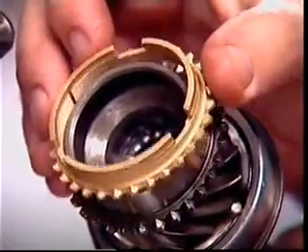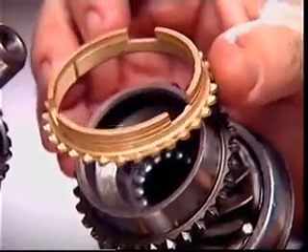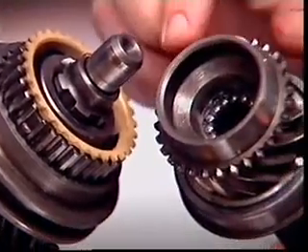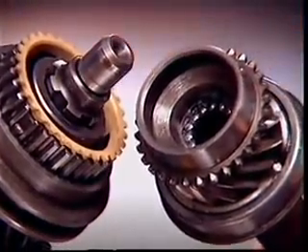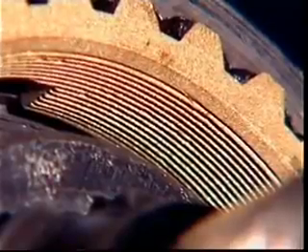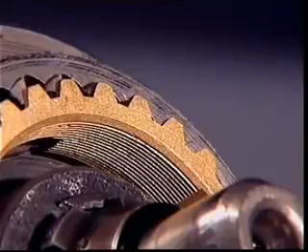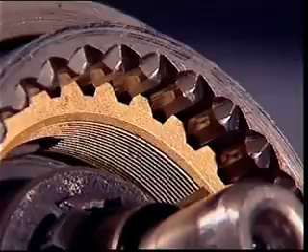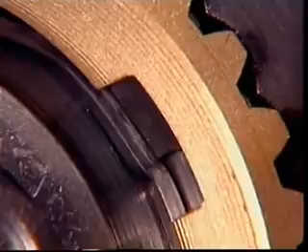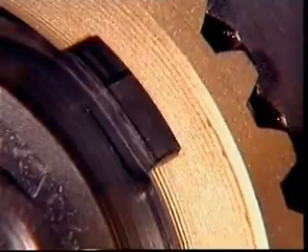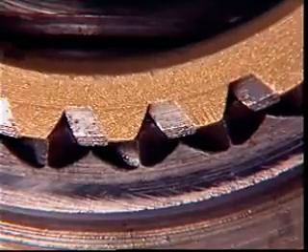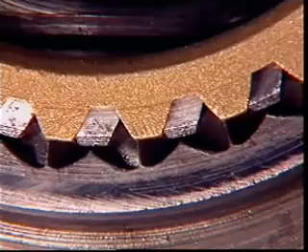A bronze balk ring with recesses to accommodate the ends of the inserts is located in each end of the hub, and a conical inner surface faces a matching steel cone on the gear. Fine grooves are machined on the conical surface, and the teeth on the outer edge are the same size as the dog teeth on the gear and the spline on the sleeve. The recesses are wider than the inserts to allow the balk ring to move radially. Then the teeth on the balk ring can be out of register with the teeth on the sleeve.